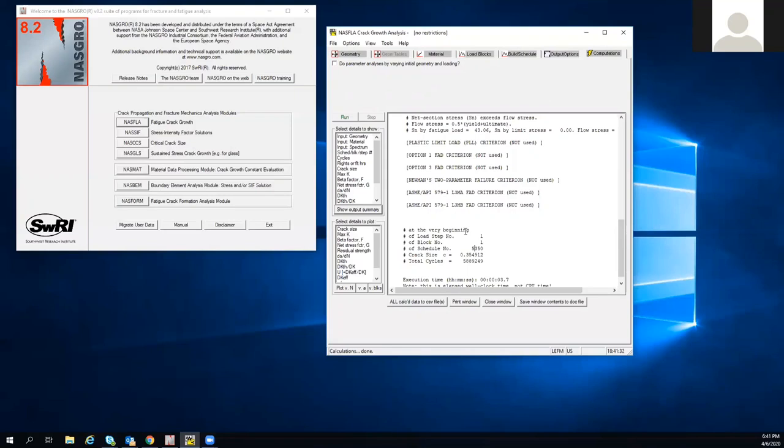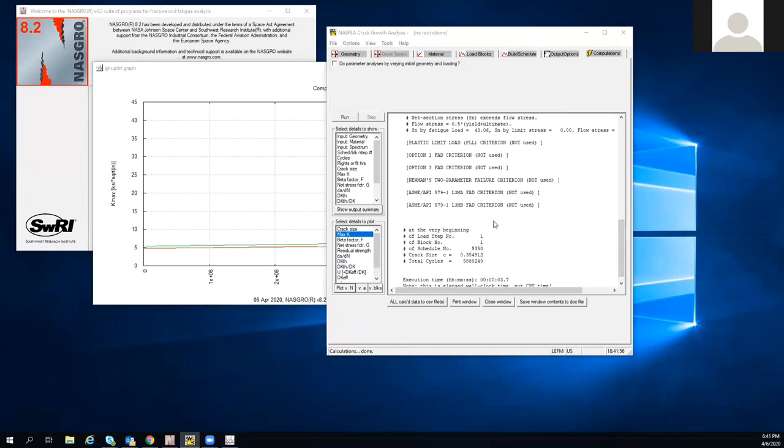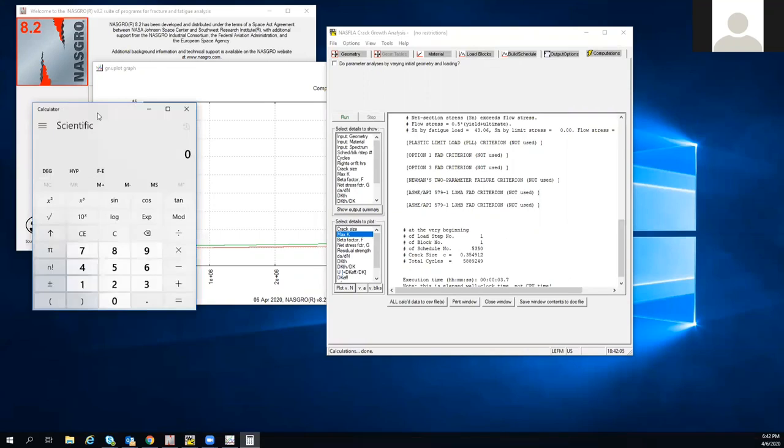The reason is because fundamentally a margin of safety calculation is an extrapolation of how much capability you have left in a linear sense. But we saw that if I look at, let's say, max K, and I plot that versus N, this is not linear. So I can't claim a margin of safety. If I were to calculate this as 5,350 divided by 10 minus 1, the standard margin of safety calculation, then this would imply, okay, I have 5,340% margin.